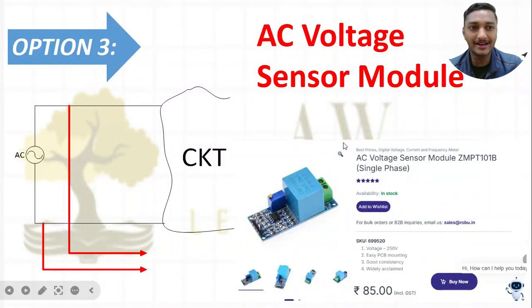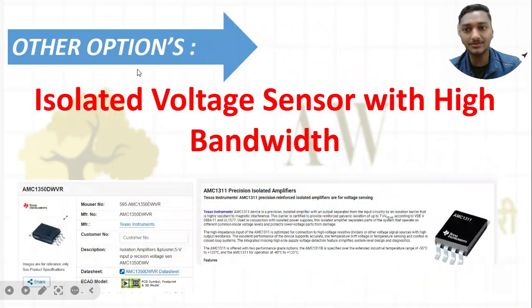But what I will recommend, if you are working on some Arduino board or some small boards, you can use this AC voltage sensor module. So they are okay to use. Okay, so this is another way. If you have some cost cutting, then you can use this. It will work. I have used this, so it will work fine, but not for very large scale applications. For that you have to use some precise ICs only, not some module. Now next is basically other options.